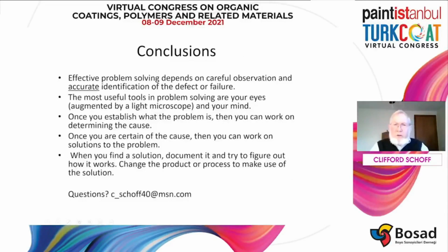So in conclusion, effective problem solving depends on careful observation and accurate identification of the defect or failure. The most useful tools in problem solving are your eyes, augmented by a light microscope, and your mind.